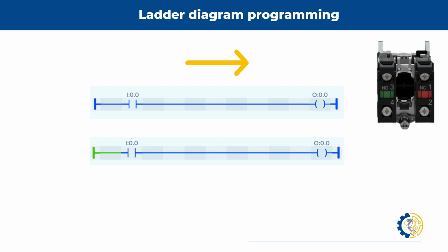If we measure with our multimeter the continuity, which is to know if we really have, as its name says, continuity from end to end through this terminal and this terminal, we're going to notice that it is open. We can't hear a thing. That multimeter sound, which is a continuity sound, if you hear that sound, then that means that there is continuity. This is normally open, guys.